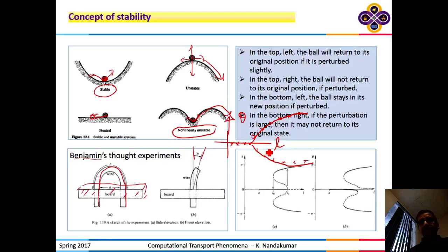But there is a solution that is also an equilibrium solution, but it is unstable. Okay? So there is a stability change at this critical point. So this point is called a pitchfork bifurcation point. There are computational algorithms that will allow us to precisely locate where that is. That is, for the control parameter length, you want to know at what length this vertical position becomes unstable with respect to this other one.